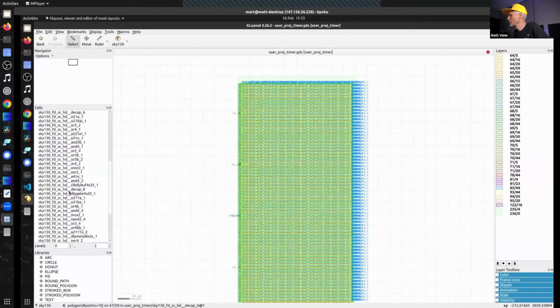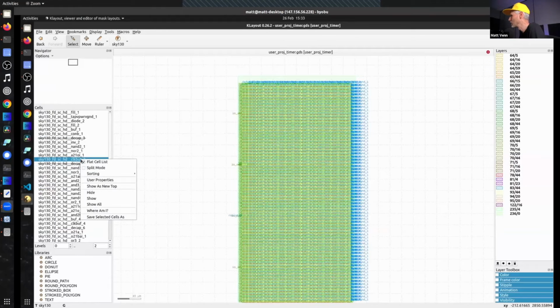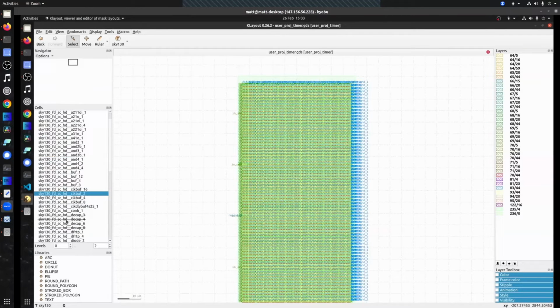Luke Vasallo asked, does OpenLane support analog I/O? Yes, it does. All the pins do support analog, but they're bandwidth limited to about 50 megahertz. I think maybe Tim's answering some of these as well, are you? Yeah, okay. Yes, I am. Right, good.